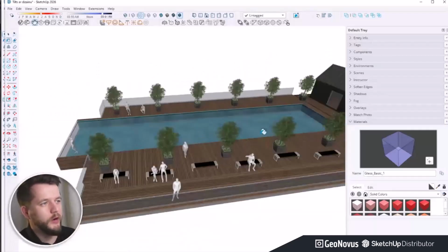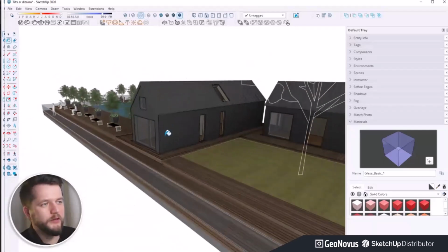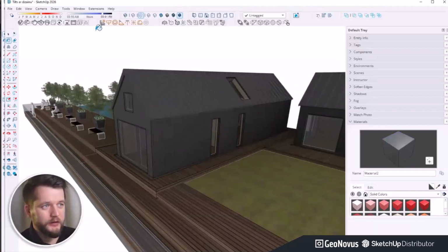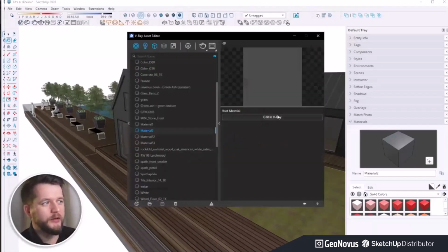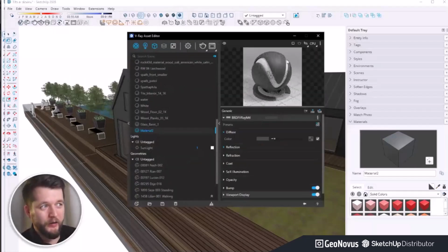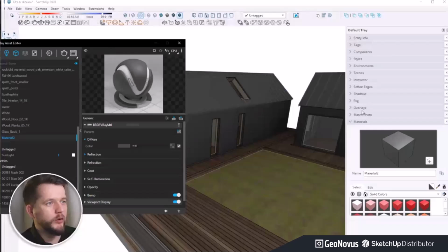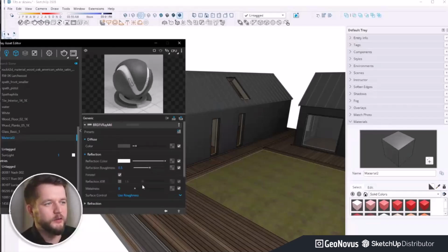And about materials in rendering, usually if you haven't already applied any kind of reflection in your SketchUp model, just go through all these objects and apply at least some level of reflection to all the faces. For instance, I see there was something applied to this material from SketchUp, but I want a bit more reflections so it wouldn't look too flat.